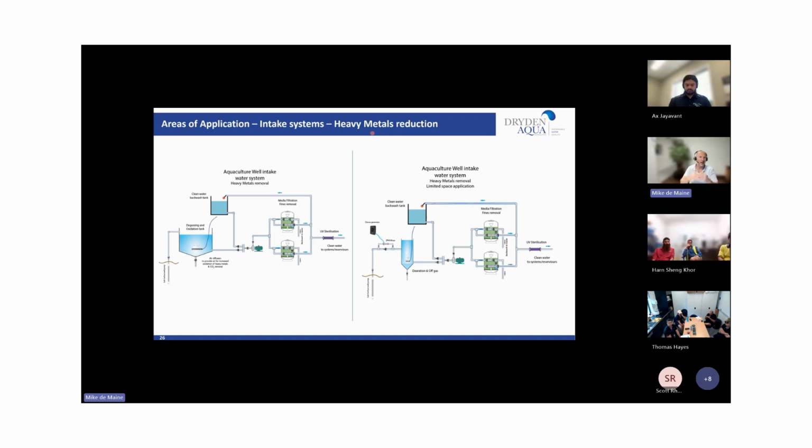Any surface can be blinded by large particles, right? So the anthracite removes those larger particles and leaves the AFM to filter the fines. That's algae, or during surge events, like I said, that can extend your run phase during these events by up to 6 times the standard run phase, right? We have calculators. I can show you our calculator as well, which will give you a good indication of your run period, depending on your TSS incoming levels.